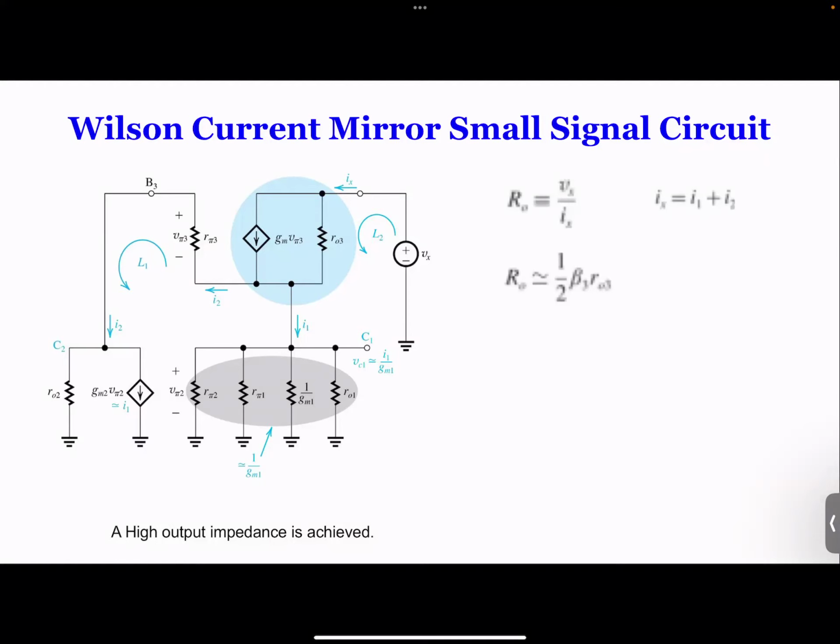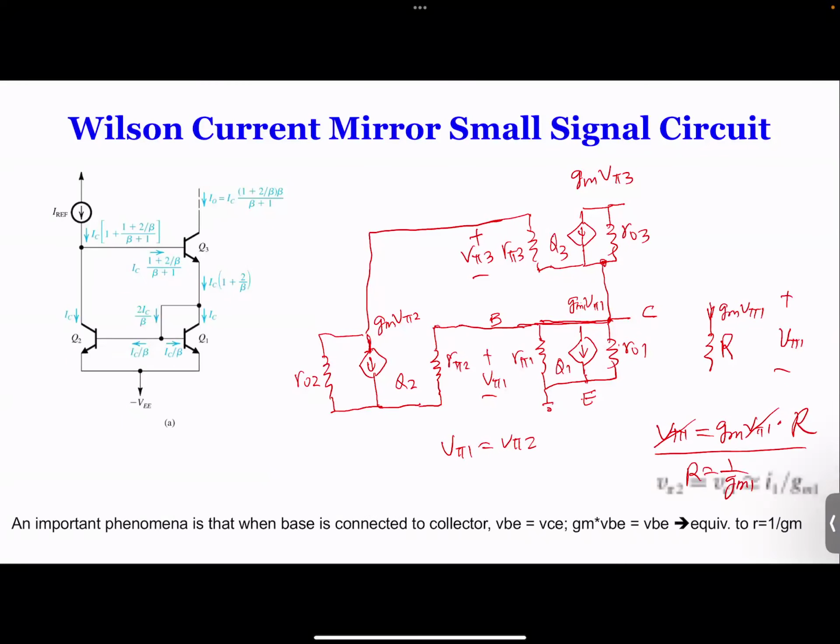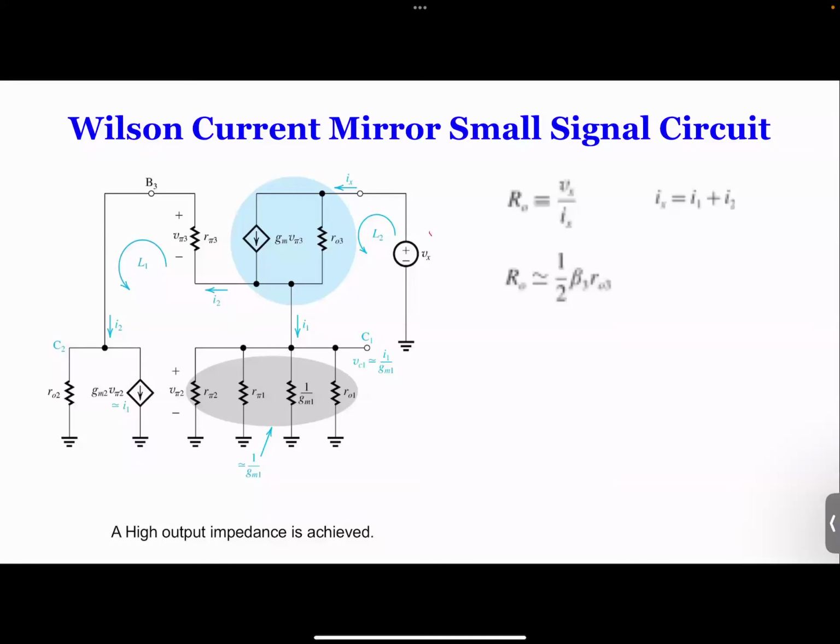So in the book, it has to do analysis to find out how much resistance we will get. If we want to find the resistance, basically the resistance is looking into here. You look at here, for example. This is where you connect your circuit. So we look at that point. So what we do is we add a voltage source, and we find how much Ix.